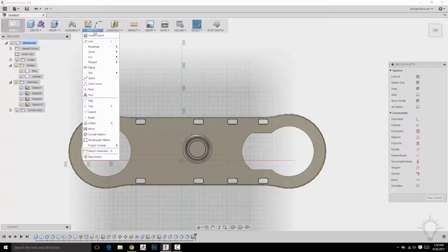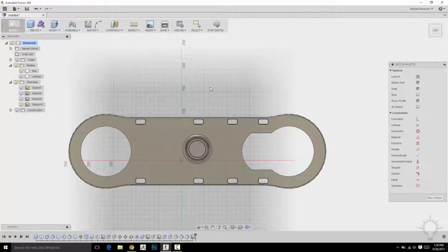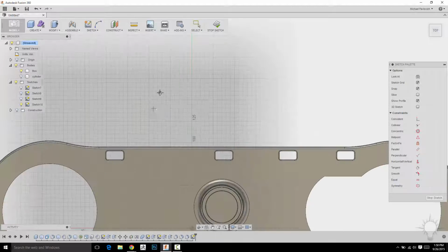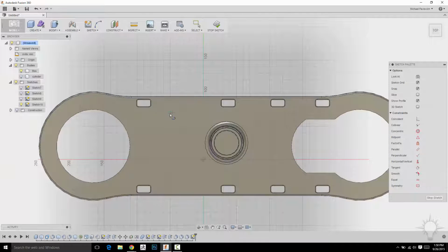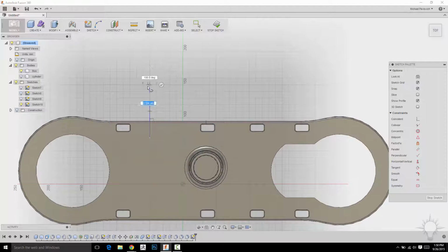And let's go back into sketch mode. And you know what, let's keep it simple. I'm going to hit L for line. And if you go through here, you can sketch, and if you want to append again to this object, you can just click in here and you can use your line, and you've got an angle and you've got a measurement here. So if you click and stop, you can now click and go another direction here, and it can be, you know, this is 0 degrees, this is 180 degrees, and it's this many millimeters.